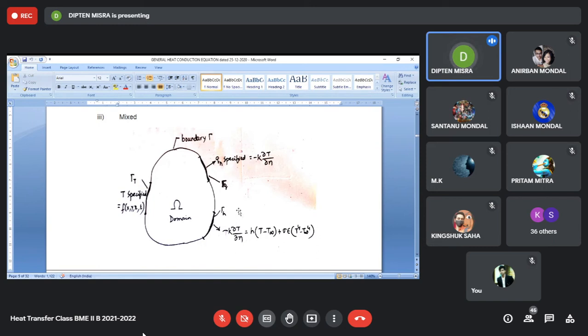Maybe the temperature gradient is also not easy to know, but by some means we can specify the heat flux. If neither is known, this is a way out, by specifying this mixed type boundary condition, given by the temperature and the gradient together, though neither the individual value of the temperature nor of the temperature gradient is known.